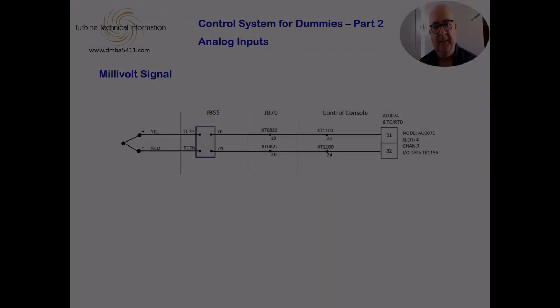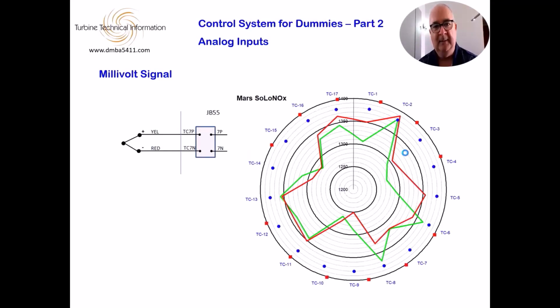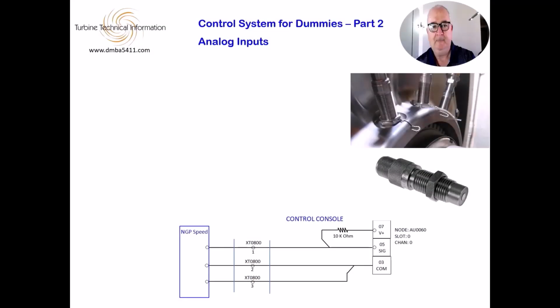Now that we've found it, it is important to look at the difference between the thermocouple and the average over time to see if there's a significant change now compared to when the turbine was tested in the test cell. This check is called T5 spread. The signal needs its own special Flex IO to process this signal.